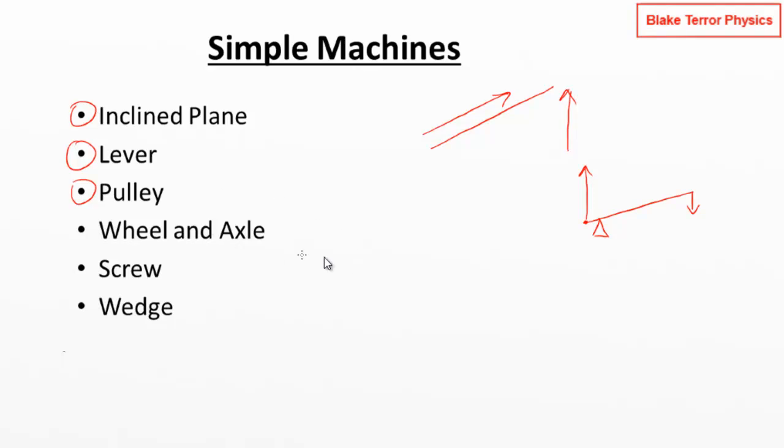Pulleys are where we're using ropes and magnifying the force on those. So you've got one rope that will be wrapping around these pulley systems. So you wrap the rope around. Here we're pulling down with one amount of force. So you think of how ropes work. We've done loads of stuff with tension, and that tension is transmitted throughout the length of the rope. So now we've got 2 lots of tension pulling up over here. So we've doubled the lifting force to some weight that's hanging off the bottom of the pulley.